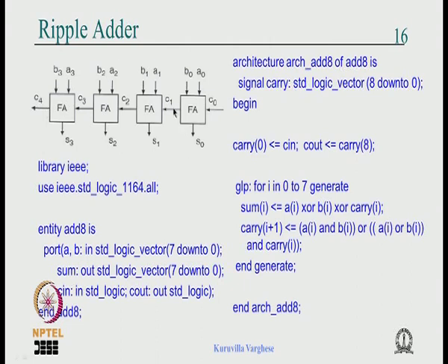So actually if you do that, what you get is a carry lookahead adder, and since that is complex, one should go for a modular approach. At least in the case of adders it is possible, because of this structure: you add something, then you have a carry which goes to the next level, and at the next level you do the same thing.